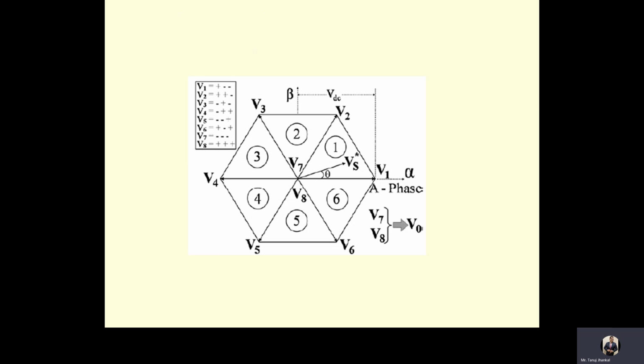In the voltage space phasor structure, the center zero inverter vector has multiplicity, or redundant switching states: for N level it will be N, and for 2 level it's 2.